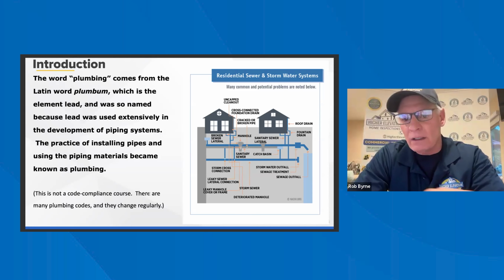Perfect example: take the hose, the shower head, and let it hit that corner, because if it's leaking, that's the only way you're going to find out. If it was just sitting on the shower head and just running straight down, you're never going to get this effect. So that's important. Make sure the doors are sealed properly.